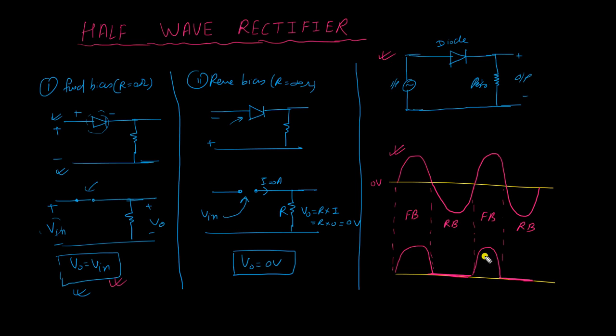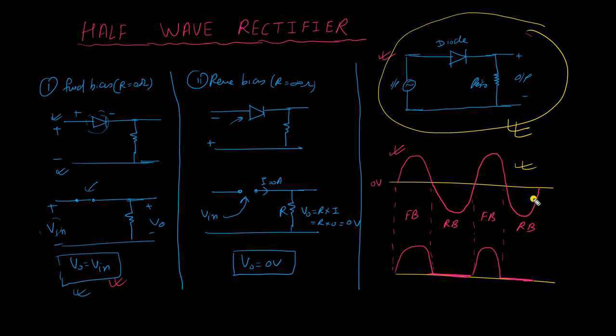Now what will we do? We will draw this same circuit in the Proteus software, and we will simulate it and see the result. We will apply various waves like sine, cosine, triangular wave, and square wave, and we will see that in case of forward bias we are getting the result like this, and in case of reverse bias we will get the result like this. And after that we will also analyze one important condition. So let us go to the Proteus software.